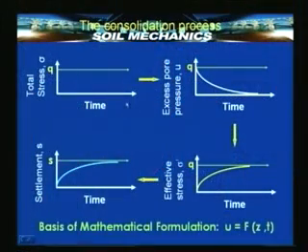And this is the progression that takes place, and ultimately this sequence of events leads to a settlement where the settlement also starts from 0 and goes on increasing and reaches a terminal maximum value at theoretically time equal to infinity. So, we have now very nicely seen a mechanical analogy and how it simulates an actual condition in the field, and very well understood what takes place when the phenomenon of consolidation is progressing.